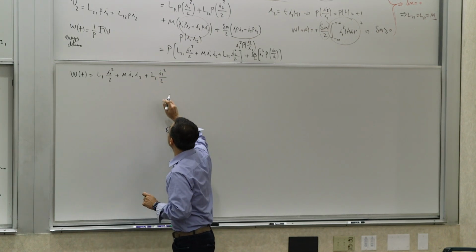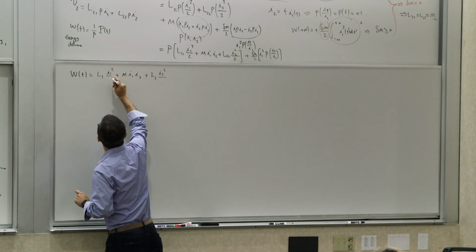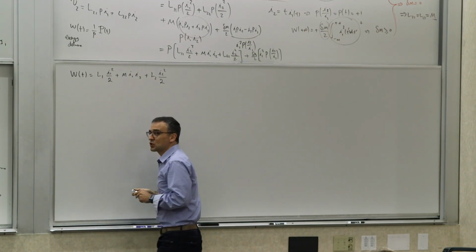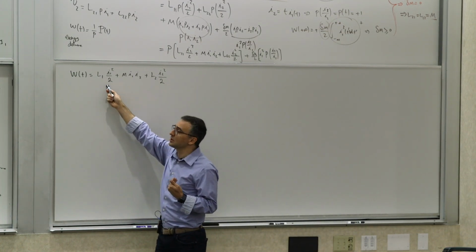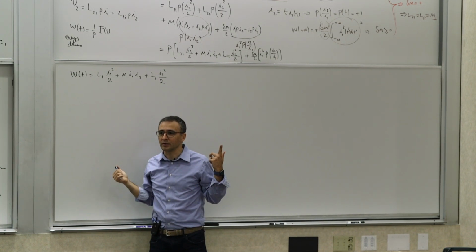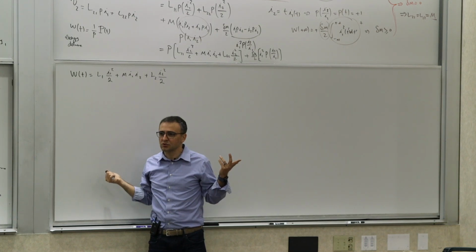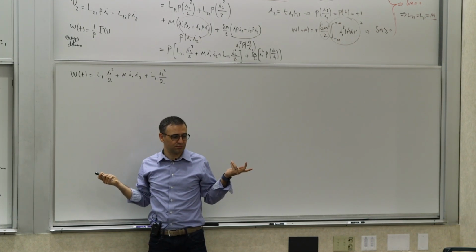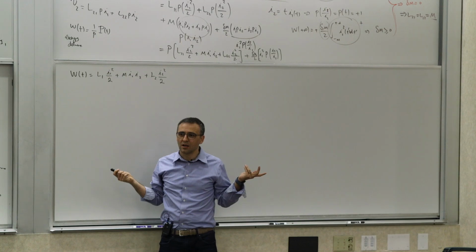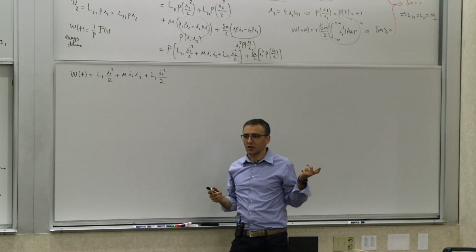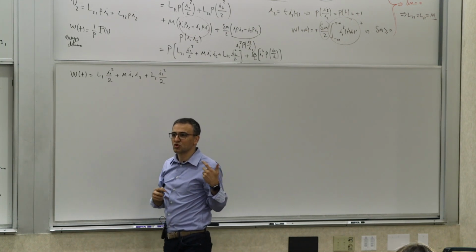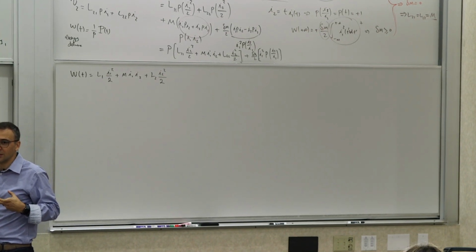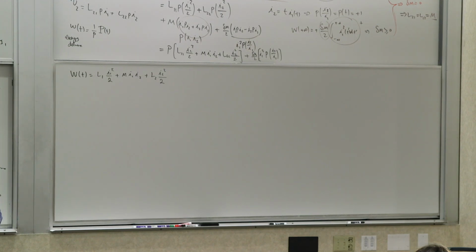So now if you look at this, this kind of makes sense, right? It says that there is really energy stored three different ways. One, the first term is the energy of an inductor. If you had a single inductor with a value of L1, what is the energy stored in it? Is it 1/2 L I squared? And also same thing for the secondary inductor. That's the energy in the secondary inductor. And then there's some energy, in principle, stored in the mutual part of this. So there's extra energy stored in the mutual coupling between these guys.